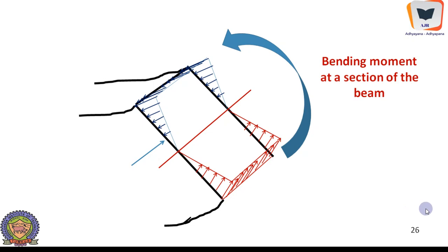Therefore bending moment at a section will create a varying stress, with the highest magnitude at the top, becoming 0 at the neutral axis, increasing in the higher order up to the bottom layer of the beam. Therefore beams are called traditionally the weakest components ever found by civil engineers, because the same material is subjected to tension and compression in different zones.